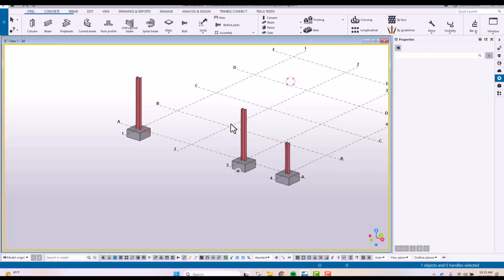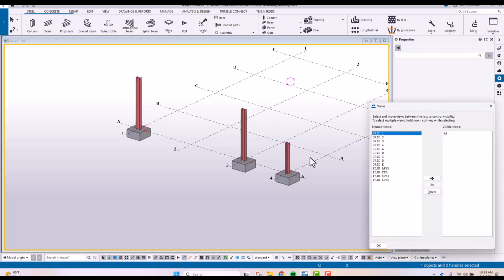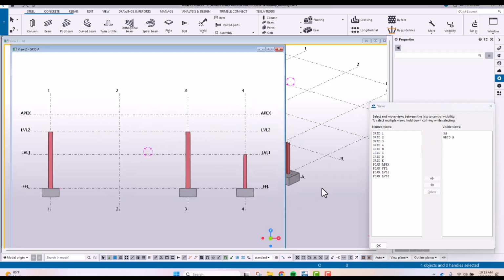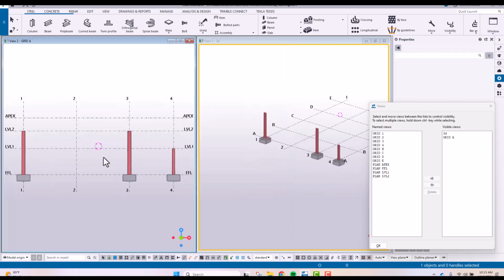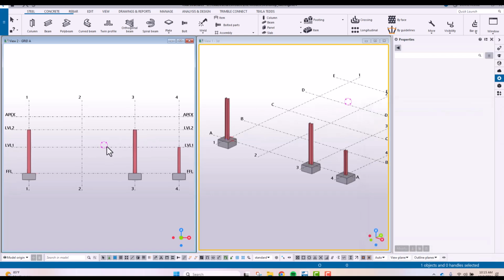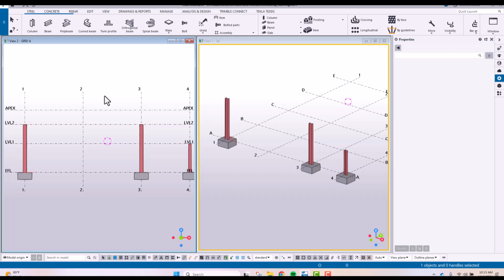If that is the case, one way is this. Go to Control I, and then open the grid, and then window vertically. So something like this, I have two views now. The easier way to do this is on the 2D plane. If you don't know how to do it in 3D, then go to the 2D.